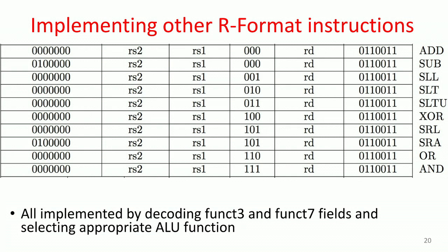So we build an ALU that can do any of these functions. And then we have some control signals that pick between these 10. So it'd be 4 control signals in the ALU to allow it to perform the proper function depending on the instruction. Okay. So those are the R format instructions.